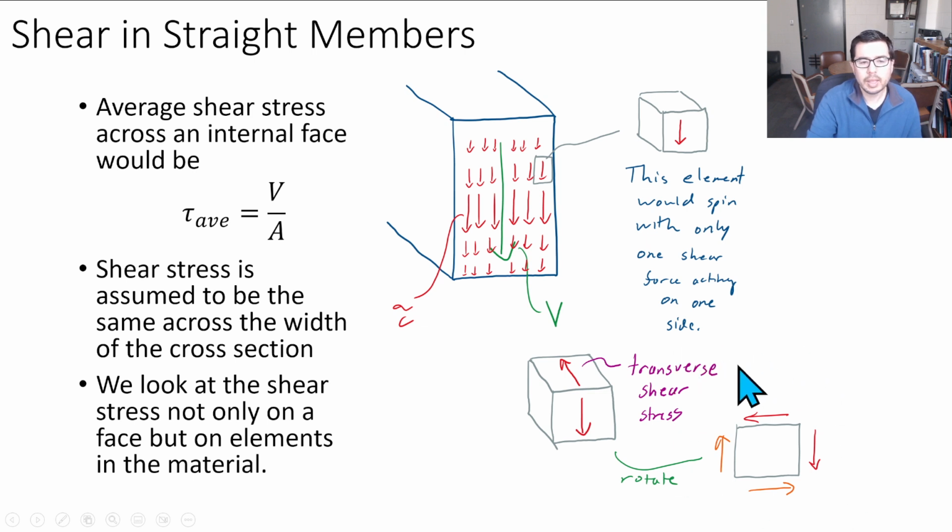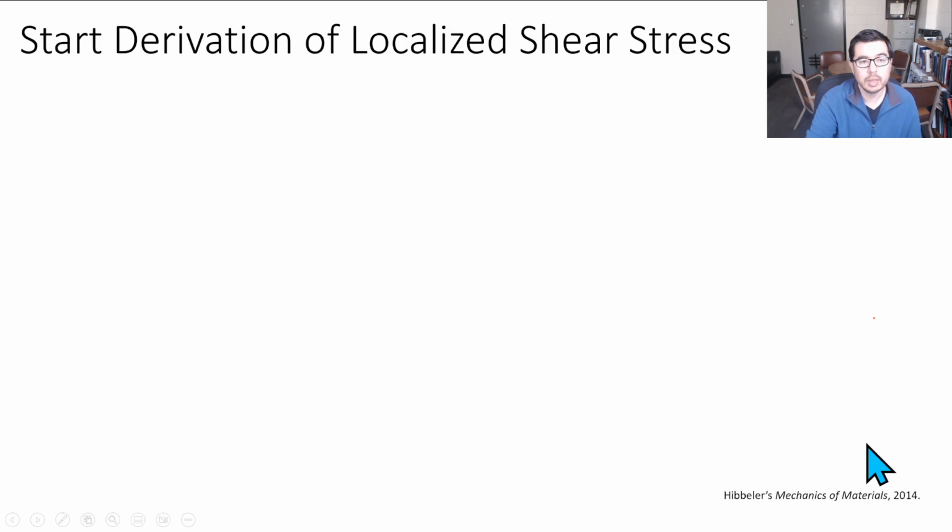If you think back to how we defined shear stress in previous sessions, we don't typically care as much about direction with shear stress as, say, when something's in compression or tension, but it is important to note that it does have a positive and negative convention that we follow. So this would actually be negative, given what we have here. If the two arrows come up to the top right corner, that's positive. If they come down and away, that's negative.